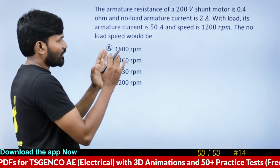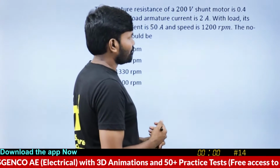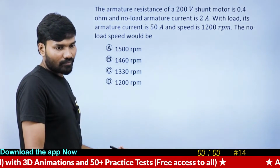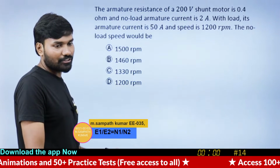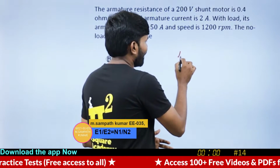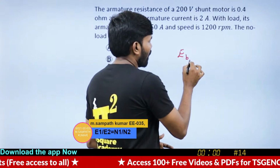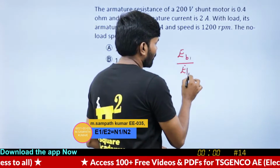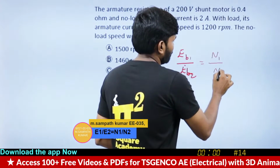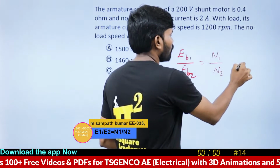Now, whenever you see a speed control question, as Sampath has said, you have to keep this equation in your head: EB1 by EB2 is equal to N1 by N2 into phi 2 by phi 1.